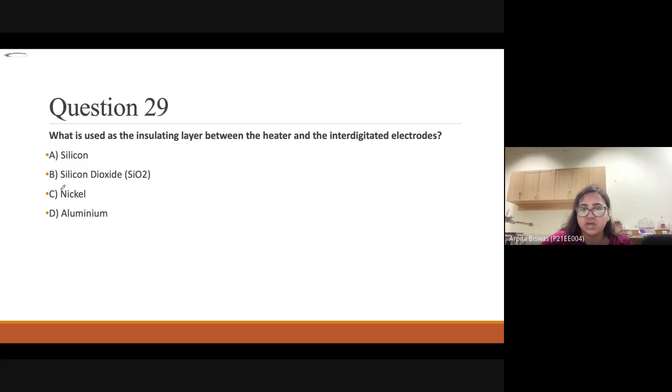Okay, so there is a nichrome or nickel micro heater present, then a thin layer of oxide, then they deposited the interdigitated electrode to stop this shorting. The interdigitated electrode is not directly sensing the VOC. Actually, when the active layer comes in contact with the VOCs, it changes its property, like its resistance or something else, and then it is measured by the electrode.